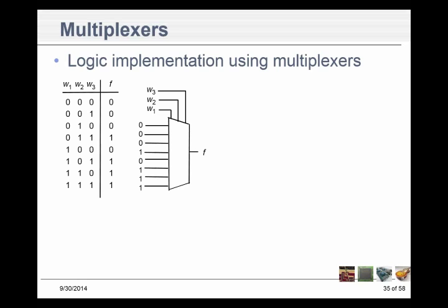We could come up with that as a summation, which would actually tell us how to hook it up as a multiplexer, right? Because the summation expression tells you what value to put on bit 0, 1, 2, 3, 4, 5, 6, 7. Just like it tells you in the cells of a K-map, this cell has 0, this pin has 0, this cell has 1, this bit has 1. They match perfectly. That's why I've had you writing summation expressions, so that you could easily go to this. So we could create a K-map, and it tells us exactly what we're supposed to do for the multiplexer, which tells us exactly what the lookup tables should look like in Xilinx.